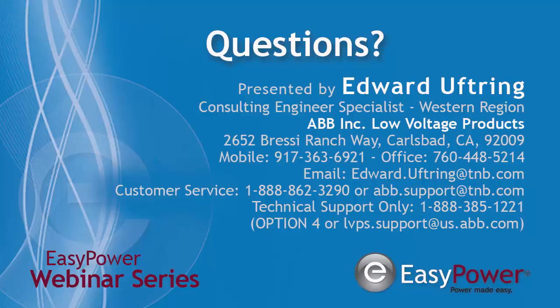So each breaker can have a rating plug stuck into it. Depending on that rating plug is depending on how we're going to be looking at the overload. We have several curves. I can get you the information on that. From there, you can actually see what we do as far as the time.